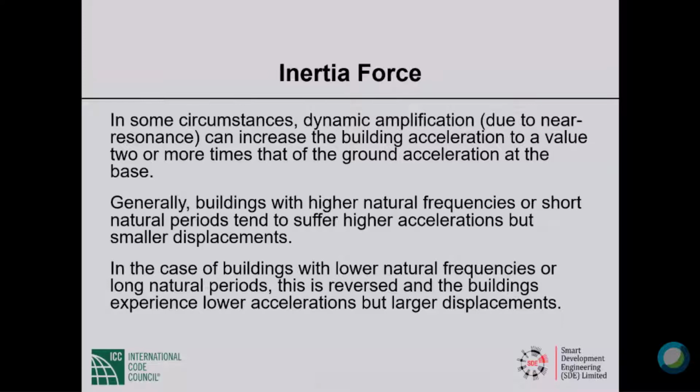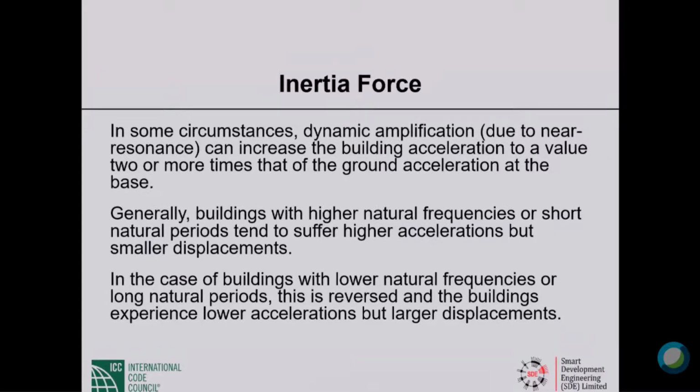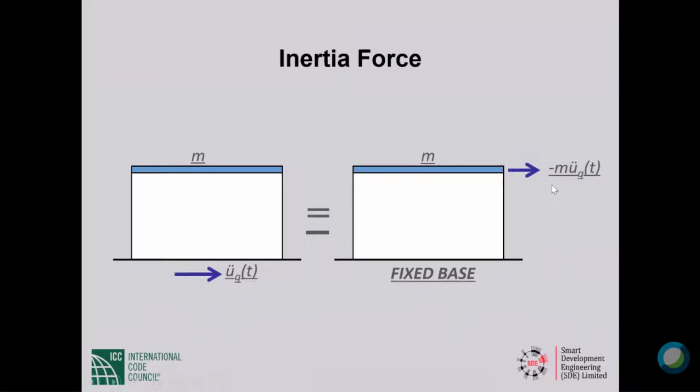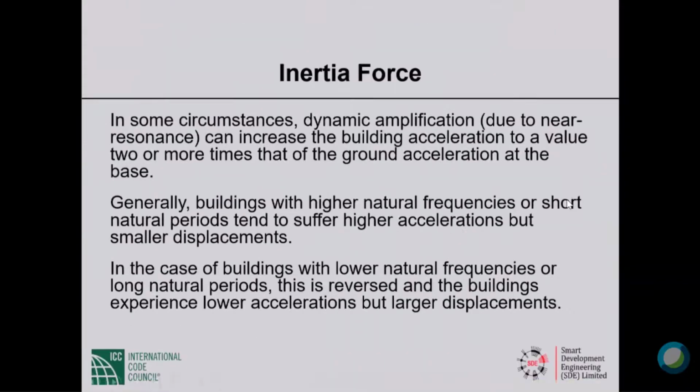In those cases, the dynamic amplification can increase the building acceleration to a value 2 or more times that of the ground acceleration at the base. So the acceleration here, particularly for taller buildings as you go up, can be many times U sub g double dot. It's not necessarily equal.